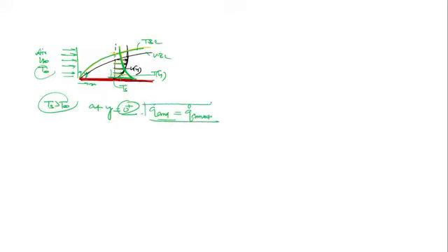Here conduction and convection are in series, meaning at the wall the heat transfer is through conduction, but in the rest of the flowing fluid the heat transfer is through convection. The rate at which heat transfers from the surface to the fluid adjacent to the surface is through conduction; the same rate, whatever energy was transferred through conduction here, is going to be transferred in the rest of the fluid via convection.